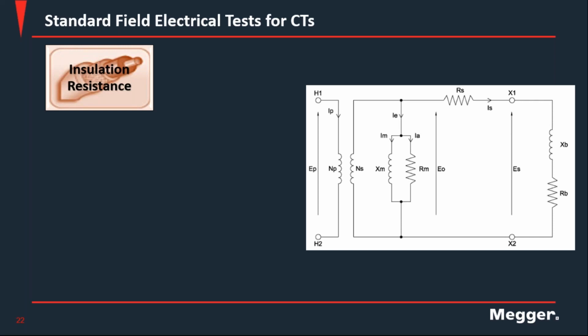In the case of the Rogowski, now you have a relationship between the current going on the primary and a voltage on the secondary. If you account for that, you need to perform tests on the Rogowski like ratio, polarity, and phase deviation, much like you would do on a regular inductive transformer. However, on the Rogowski, there's no saturation, so you wouldn't be performing any saturation tests.